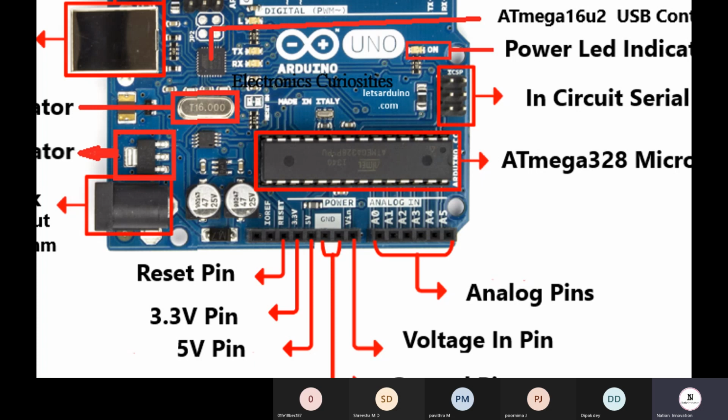So in Arduino, we have a resolution of 10 bits. Whenever we provide any analog signal, the Arduino will read that value from 0 to 1023. How it does that: it takes the analog value, and the internal analog to digital converter converts that value to a range of numbers. This range comes from the resolution, 2 to the power 10, which is 1024 total different values, starting from 0 and going up to 1023.